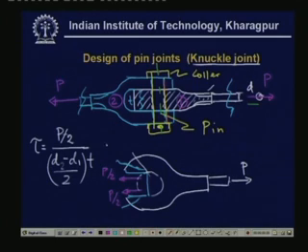So this shear stress must be less than allowable shear. So this has to be satisfied, and once this is satisfied, then it will not fail in these configurations. So this is one such failure theory. We have used again the failure theory, that is this material breaks for maximum shear.